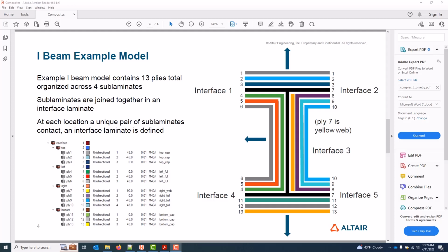And then we'll finish with the steps unique to this complex tooling geometry modeling process, specifically how we define interfaces, or how the sublaminates come together and join ultimately. And we'll do some manipulation of what we call Plies Normals to achieve consistent orientations where the stacking direction on a given tool is not consistent. When everything's fully defined, we'll finish with visualization to verify that all the new input we've provided is correct.